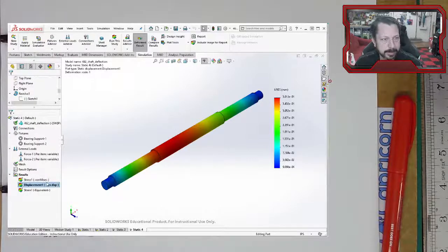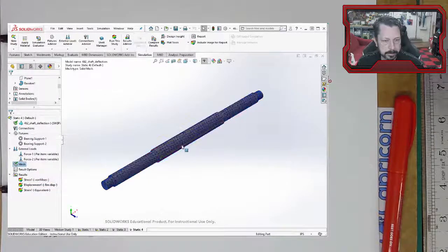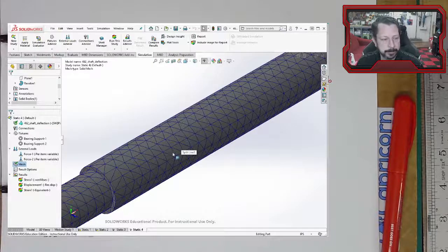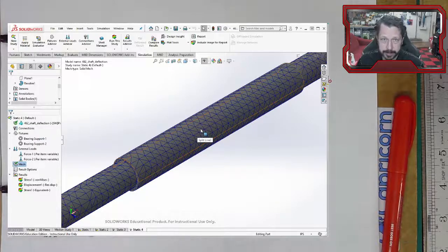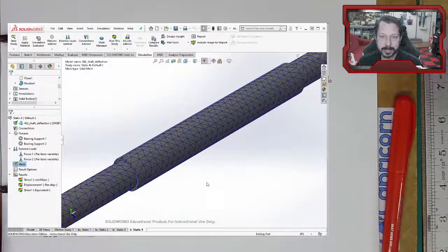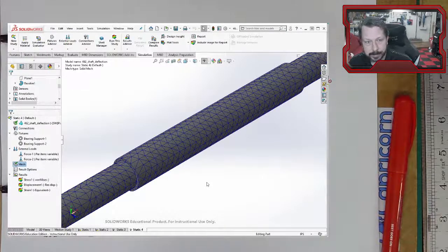Normally, when you're doing a finite element analysis, there's a whole process of mesh refinement, or at least testing for convergence. You run it at a low resolution and then a little bit higher resolution, meaning smaller elements. These little triangles are elements. I guess they're actually tetrahedra. You get them gradually smaller and smaller, and then test what it is you're interested in, deflection or stress, von Mises, whatever it is, and plot that to see if it's converging to a solution or if it's just giving you random numbers or they're oscillating.